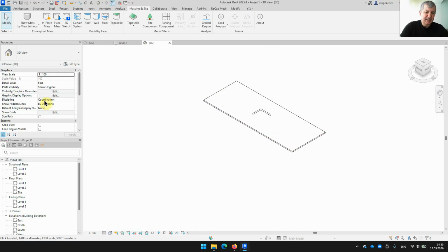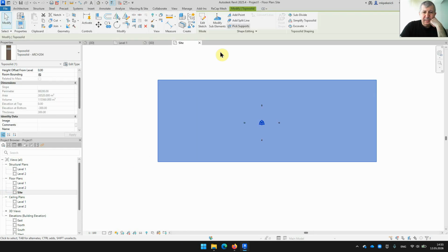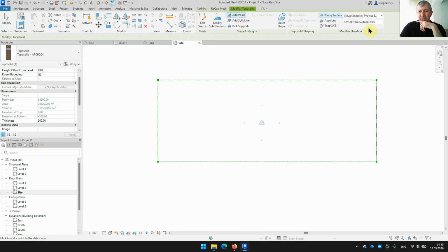We go to the site plan view. Okay, take this one and then add points. Okay, now here let's define where the 0 is. 0 could be somewhere in the middle, like we can put points for 0, like as you can see it's 0 now. 0, 0, like these points will basically determine where this 0 line is. Okay, like that. Okay, now let's add plus 100, like 1 meter from 0.